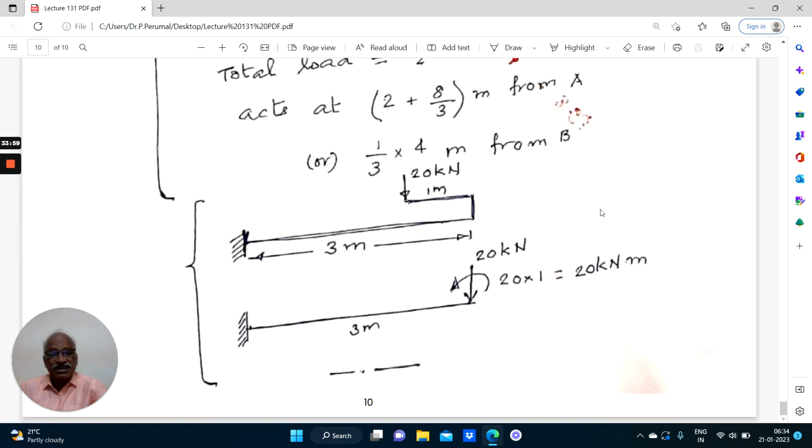So, already we have discussed a beam with a vertical member plus a horizontal load. Now coming to this, here a bent is provided like this, and here you apply some load, because you have got so many complicated structures, how the load will get transmitted and how we have to deal with that loading. The basics is very important, right? Suppose there is a load here. Now this is equivalent to a vertical load 20 kilonewton here plus an anti-clockwise moment 20 into 1. So an anti-clockwise moment 20 into 1 kilonewton meter.